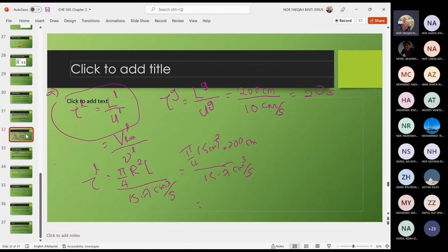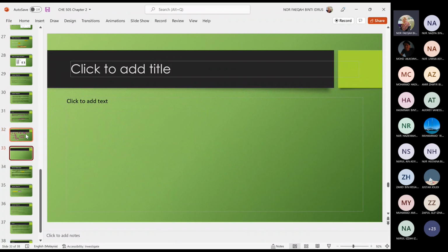Okay, next, what you need to do, because it says write the mass balance equation. Negative Rg in the gas phase equals 0, as there is no reaction in the gas phase. But in the liquid phase, negative R equals kL CAL CH2L.